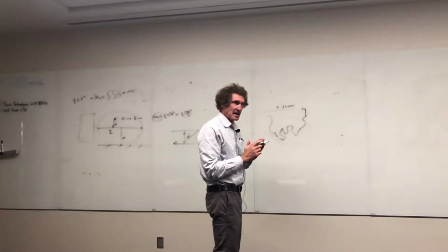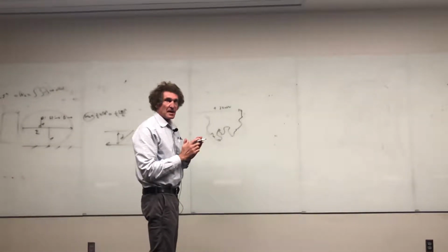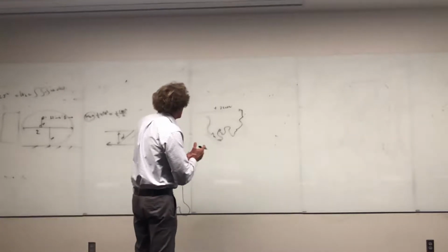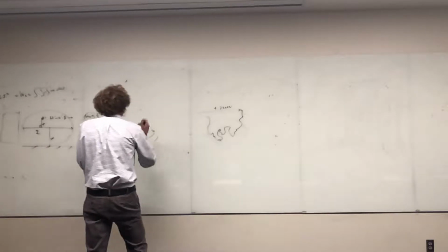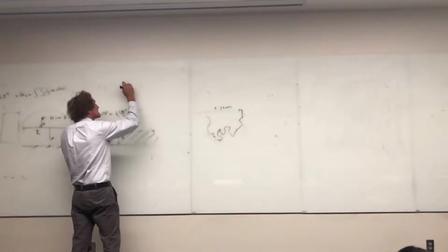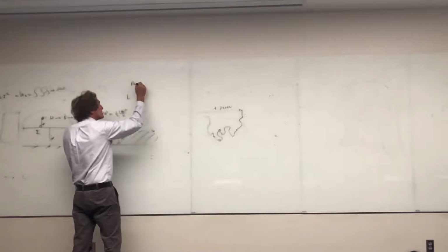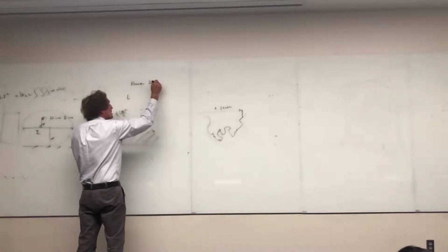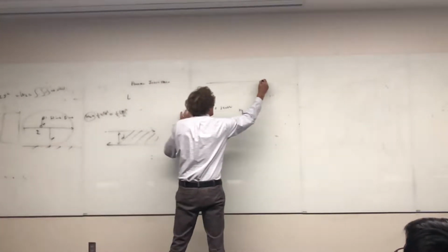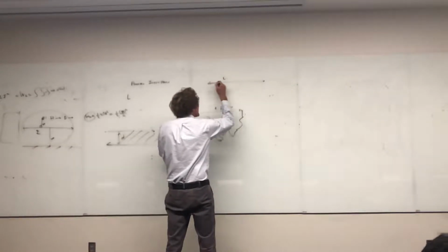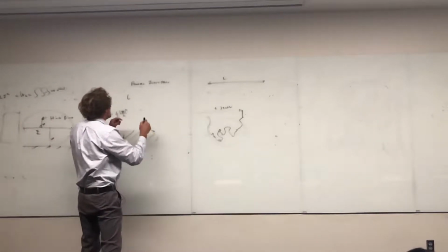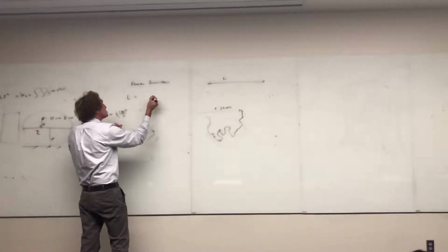They said we can estimate the inductance of wires, even with filing cabinets near them and grounds and stuff like this, by using the partial inductance formula. And now you write this down, it's in the book. It says L, this is for partial inductance. And I might add, this has to do with a straight wire of length L. Forget the wire gauge, it doesn't matter. It's going to say it's equal to,